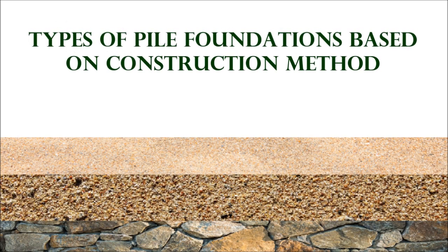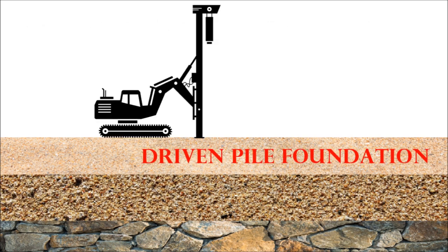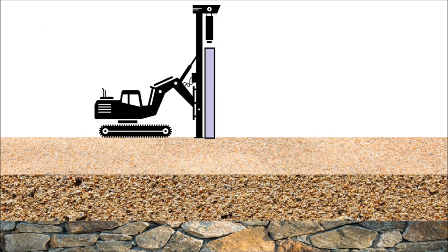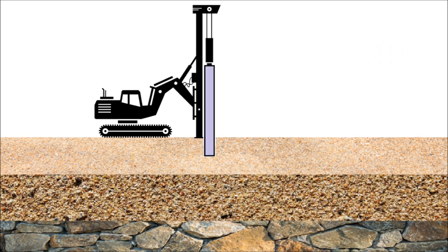Types of pile foundations based on construction method. Driven pile foundation. Driven pile foundations can be made from concrete, steel, or timber. These piles are driven using a pile hammer by dropping weight or vibrating.